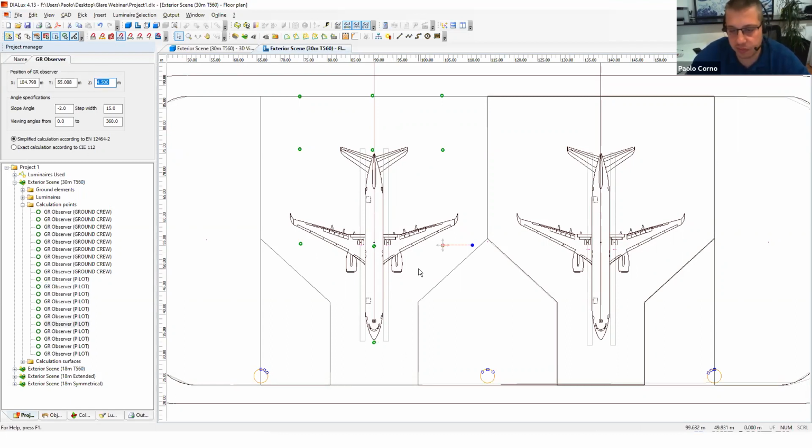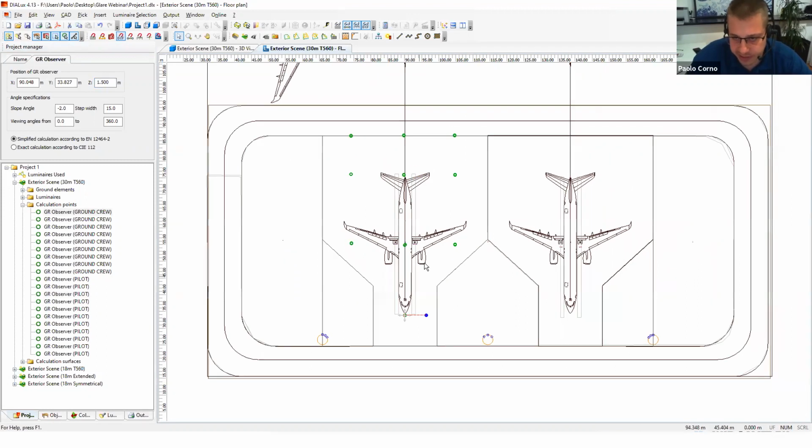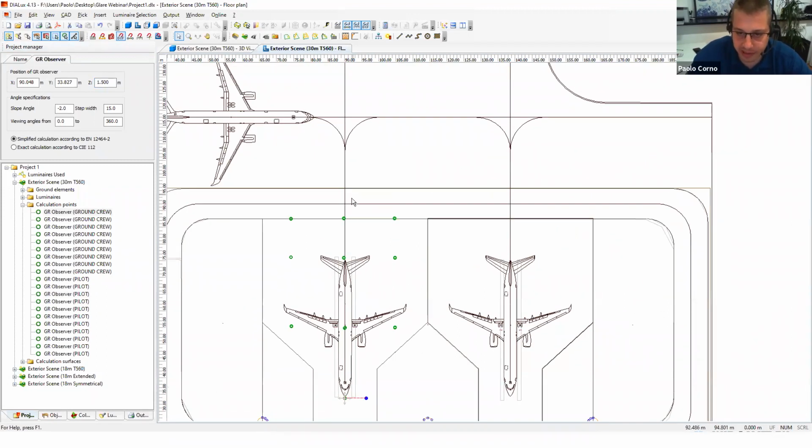Of course, you will have to go look at what class of apron we're looking at, see what the maximum acceptable cockpit height is there, and use that height. Here is just an estimation; 4.5 meters should be something like an Airbus A330. And here the most important values are going to be the ones along the center line, because this is where the pilot will actually sit.